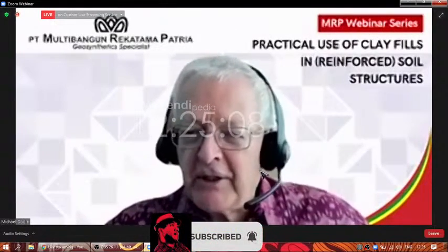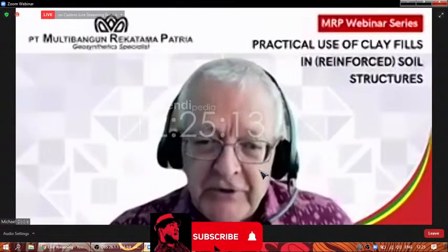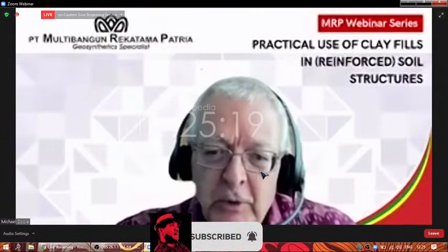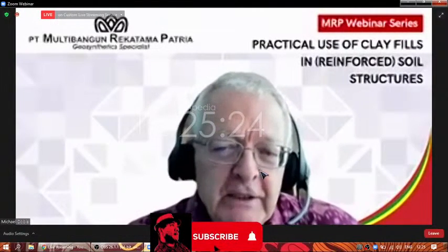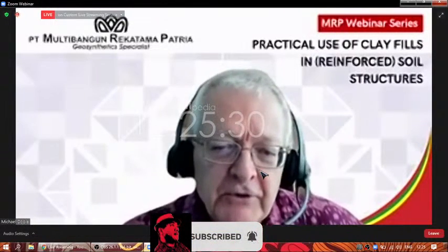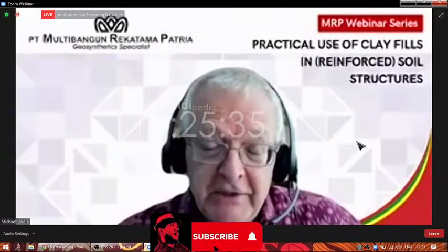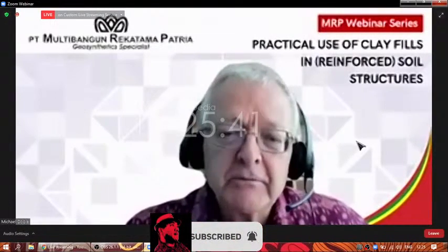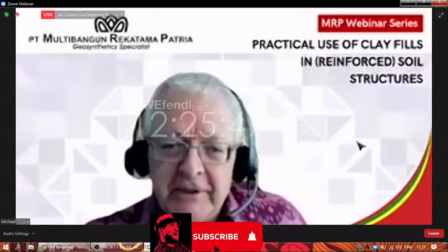Also, you'll tend at roughly that stage to switch over to full saturation. And then once that clay has become fully saturated, of course, the pore pressures can respond much more quickly, because you don't have that effect of the softer pore fluid, meaning that some of the increase in stress is carried by the soil skeleton. So at high embankment stresses, in other words, towards the base of tall embankments, you may well switch over to positive pore pressure, and you may well switch over to full saturation. And these things need to be thought about very carefully, especially with regards to basal drainage.